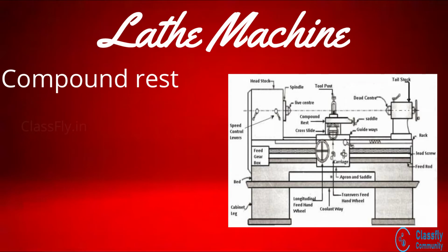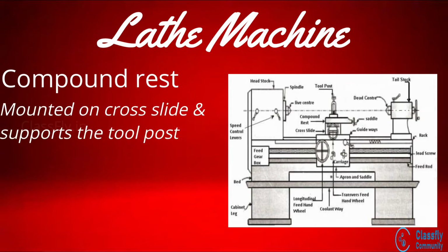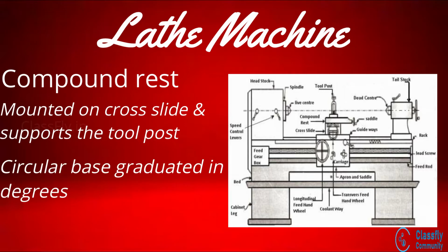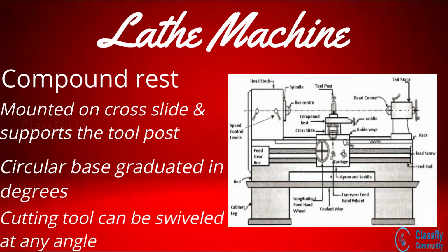Compound rest. Well, this is mounted on the cross slide and supports the tool post. The compound rest has a circular base which is graduated in degrees. Hence, this helps the cutting tool to be swiveled at any angle to obtain taper surfaces.